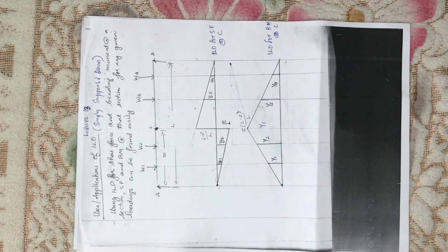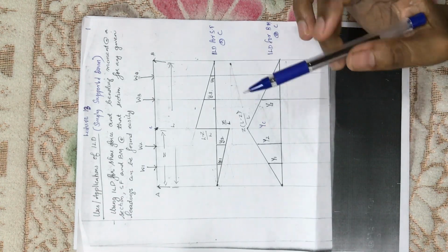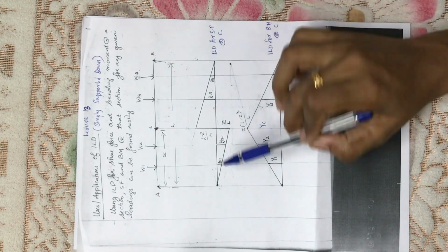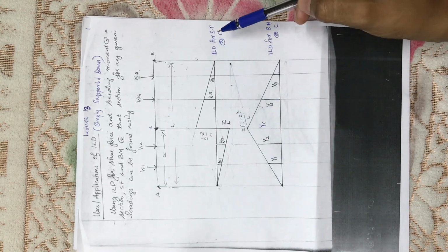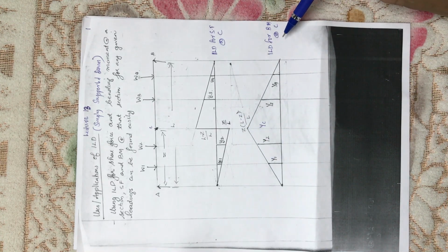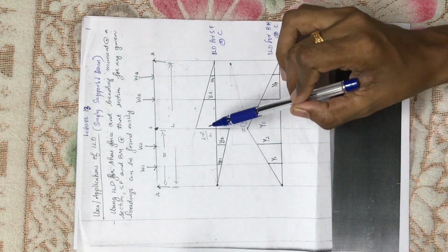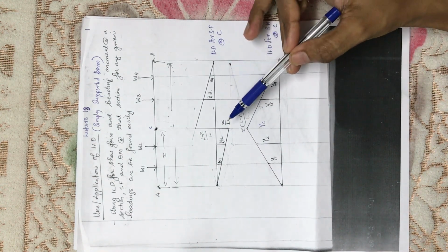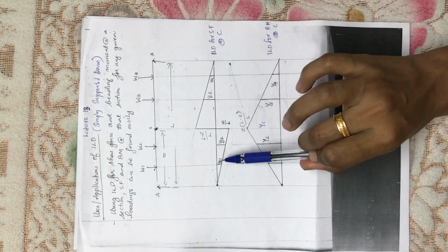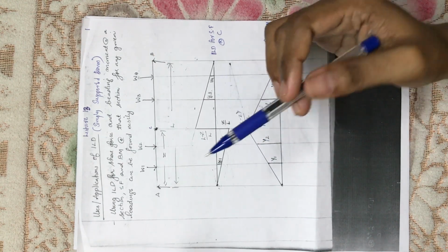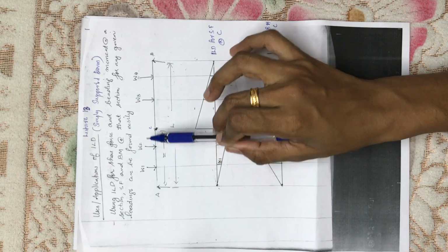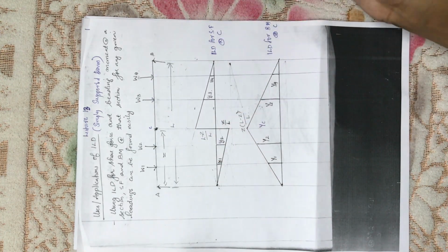Okay. So these are the values, and first of all we need to draw the influence line diagram for the shear force and also for bending moment, and by using these ordinates, that means L minus Z by L and Z by L, find out the other ordinates Y1, Y2, Y3, Y4 corresponding to the loads W1, W2, W3, W4 for shear force.